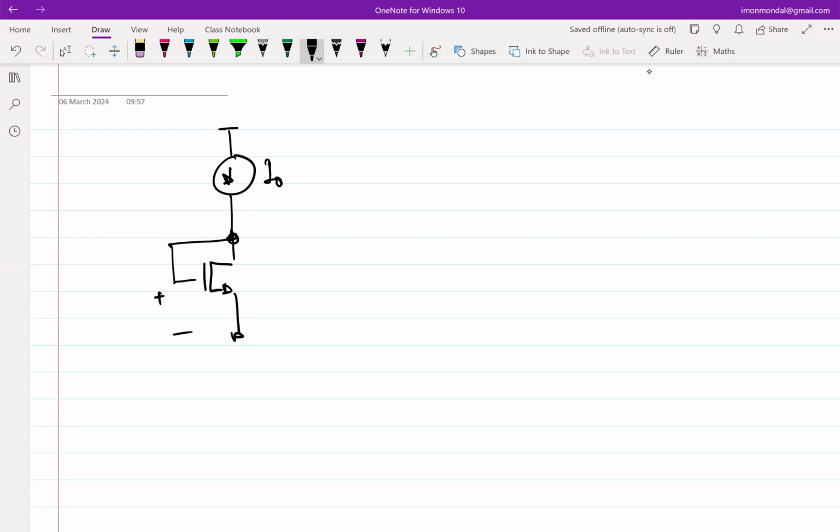So again, if the threshold voltage, for example, increases because the temperature increases, what's going to happen to the VGS? Let's say the threshold voltage increases after you biased it like this. It will increase, right? It will either increase, decrease, or not change. So it's going to increase because in order to keep the current the same, the overdrive has to remain the same. If the threshold voltage increases and the overdrive remains the same, VGS has to increase.